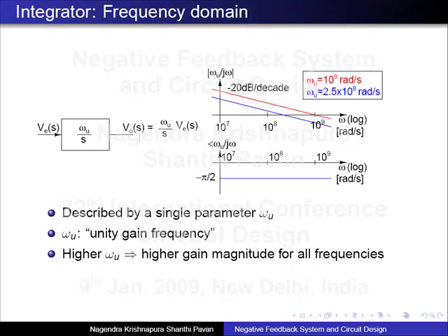If the variation of input is some arbitrary function of time, it becomes very hard to analyze. You can solve the differential equation numerically, which is what simulators do. But what we are more interested in here is getting some intuition on how things behave. So again we resort to the old technique. We assume that the input is some sum of sinusoids. Once we analyze one sinusoid, or sinusoids of different frequencies, we can put them together and find out what happens when you apply all the sinusoids simultaneously. And to do this analysis for sinusoids, we resort to the frequency domain as usual.